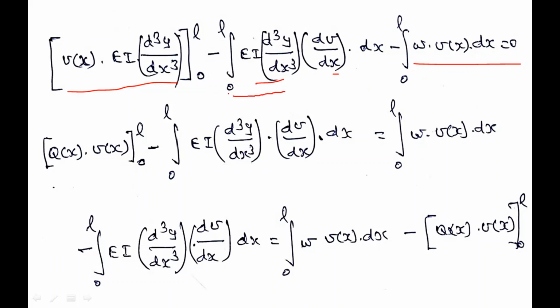You see that the fourth order differential operator is reduced to third order. We have to apply this integration by parts formula once again, and then this third order differential operator will be reduced to second order. Before that, we rearrange these terms. EI d³y/dx³: what is the physical meaning of this? The third order derivative of the transverse deflection is nothing but the shear force.